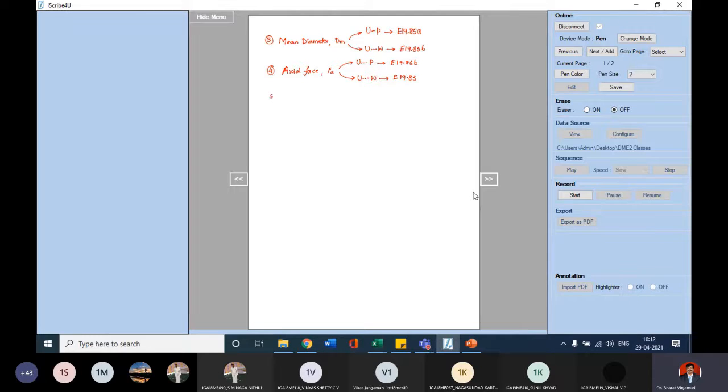Your fifth and last equation is the torque transmitted by the clutch, which we call MT. You have this equation as equation 19.84 from the data handbook. These are the 5 equations we will use. I cannot say you must follow the same order; the order can be interchanged depending on the situation.